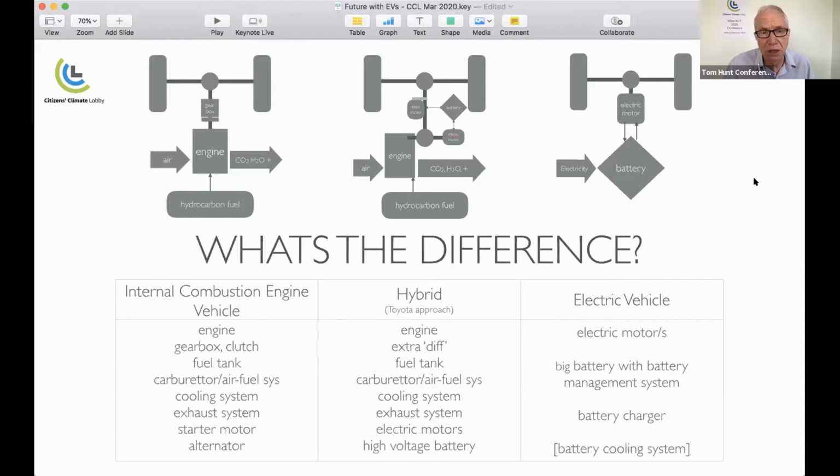And of course, hydrogen, we can just briefly say about hydrogen cars here. Hydrogen cars are effectively an electric car. Instead of having an engine to take you a little further, like a plug-in hybrid, you have basically a store of hydrogen in place of hydrocarbon fuel, and you have a fuel cell, which converts that more directly, just pulling in air, pulling in hydrogen, creating water only, and putting power into the battery, which then powers the car.